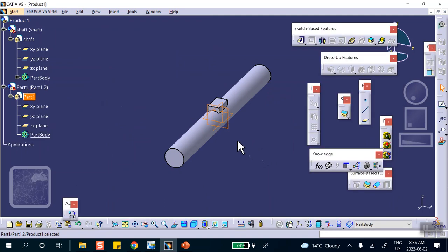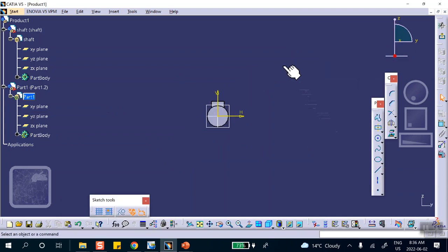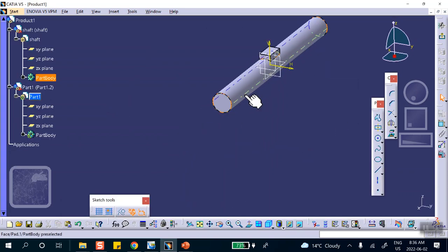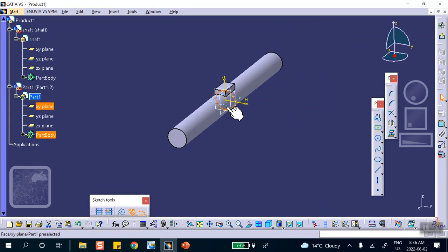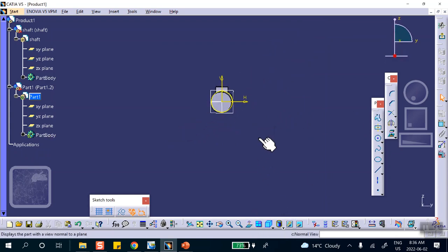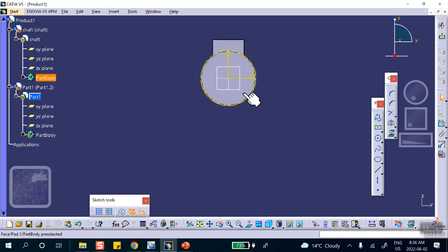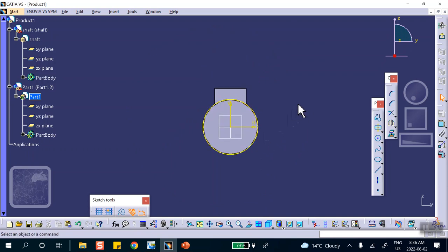So on that vertical plane, I will sketch. Why don't I project, because I'm lazy, I'm going to project this circle. Automatically, the circle is over here instead of me drawing it and dimensioning it. And now we're going to do the rest of the problem. It's yellow because it's a projection. Good question for the test. It's yellow because you circle the right one.